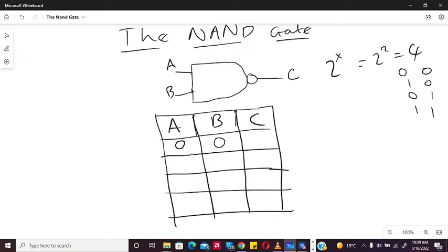What do you think the output at C will be? This is not an AND gate whereby we can simply use some rules and that. This is actually different. So if you get stuck, like I am stuck here, you can think of it, what's the output of the AND gate? And to make things simpler, we can actually separate the NAND gate into what it's actually made of, into simpler terms, like that. So simply an AND gate and a NOT gate.